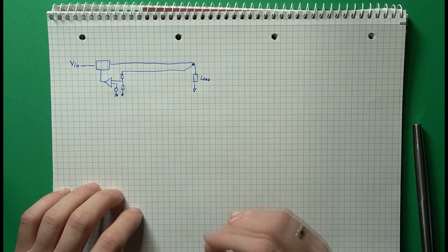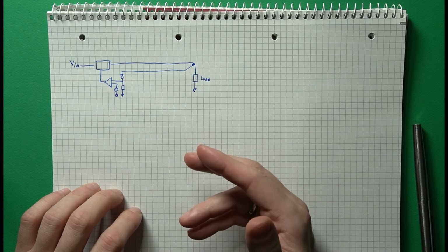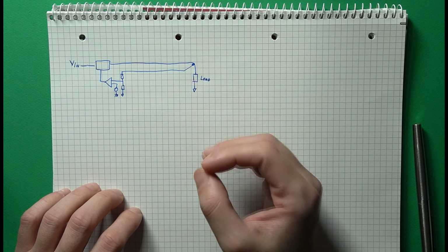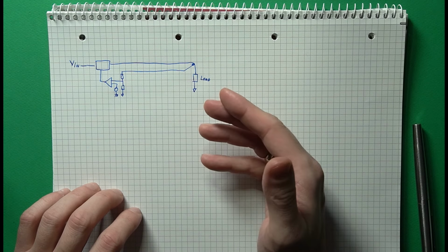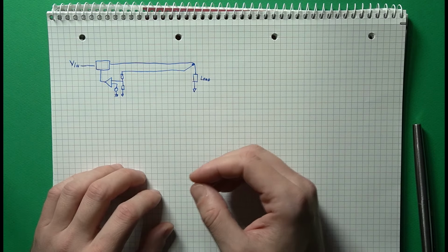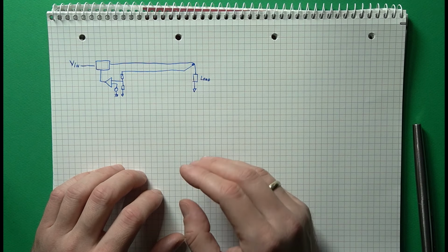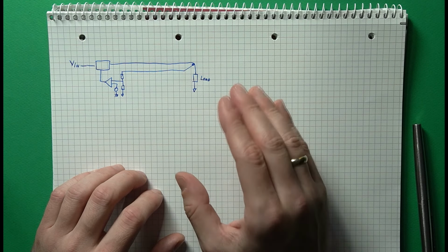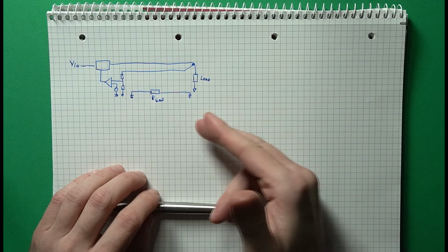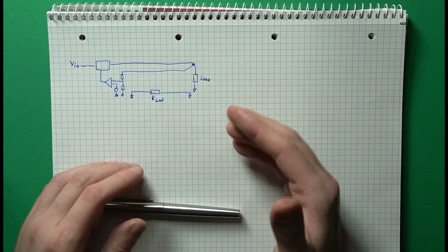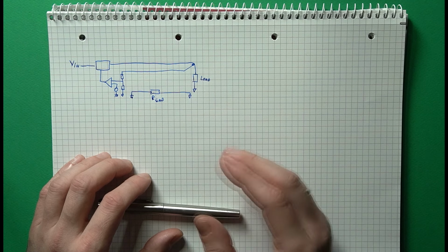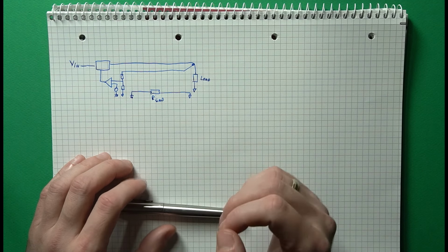However, it's a common feature present in higher-end benchtop supplies or with high-current PCB-based supplies. Now, there are two main ways in which you can do this. First, you can only measure the regulated line by extending the measurement wire all the way to the load. In practice, you might also have some extra components close to the power supply to filter out noise and ensure stability, but the idea here is to regulate the average voltage that is present at the load. This approach has, of course, the disadvantage that the reference ground line can still provide some amount of voltage offset. But regardless, this is better than the direct measurement at the power supply output.